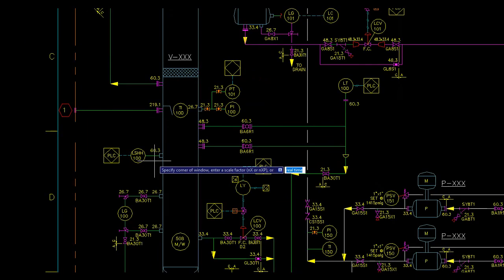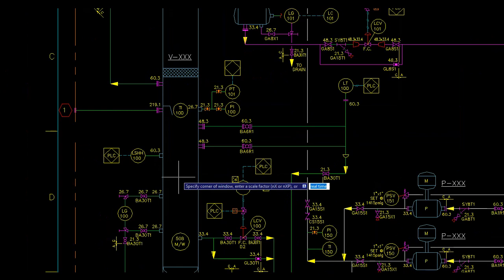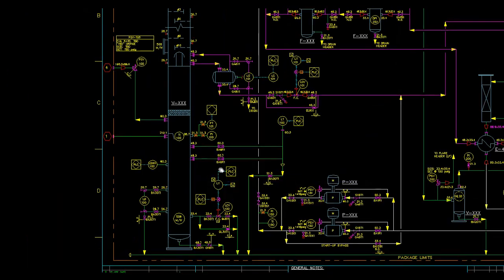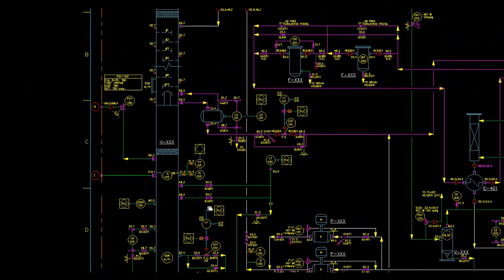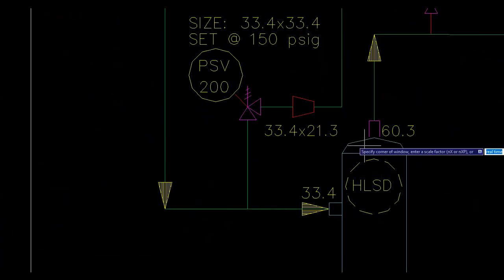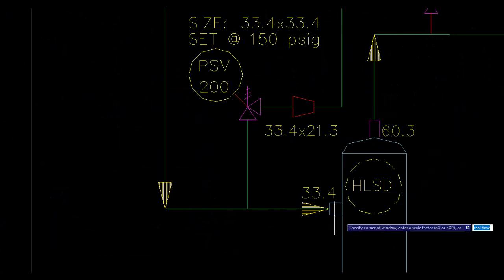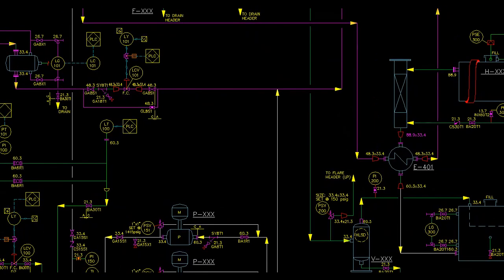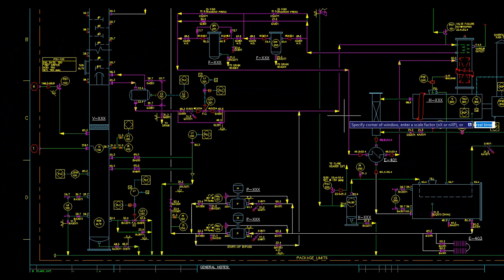As I mentioned before, liquid only comes because there is an upset upstream of the glycol skid. There is also a shutdown at high liquid level in the flash tank. There shouldn't be any liquids here. Probably this one is never activated in the entire life of the dehy, but it's a safety requirement necessary there.